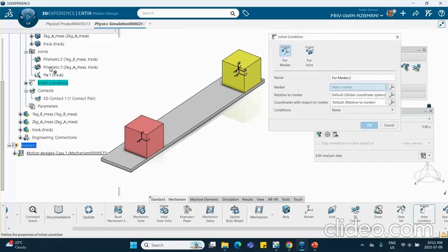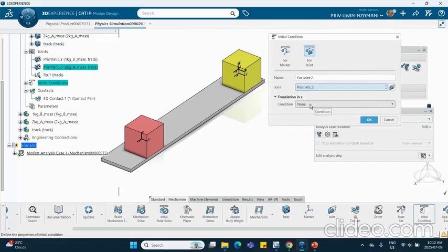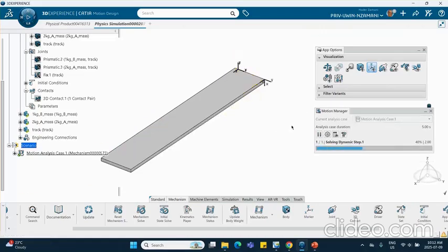This is for the other joint. For this joint, this was a 2 kilogram mass, and we are going to give it velocity, and then we're going to give it a -1. Now, if they go in the wrong direction, then we have to flip the signs. Okay, let's check it out first of all. There's the preview. You can see that preview animation. Just give it time. Yep, wrong direction. Okay, no problem.